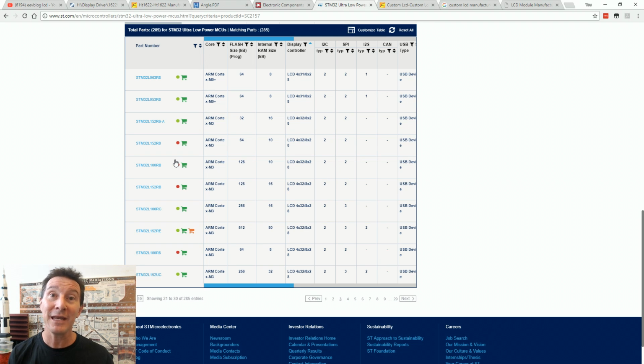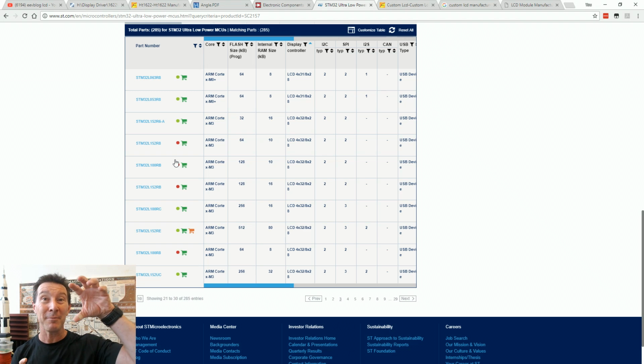You're winning. And of course, having a separate LCD controller chip can also have advantages in that you can physically place the chip somewhere else on the board, like actually under your LCD itself. So you get a nice routing of your pins and everything. You know, they fan out quite nicely to the pins of your LCD, for example. Whereas with your micro, you might need that somewhere else on your board, and then your LCD might be up here, and your micro needs to be down here for other reasons, you know, because it's got the ADCs built in that you're using, and you've got to get all these LCD lines right across the PCB. It can be a pain in the butt.